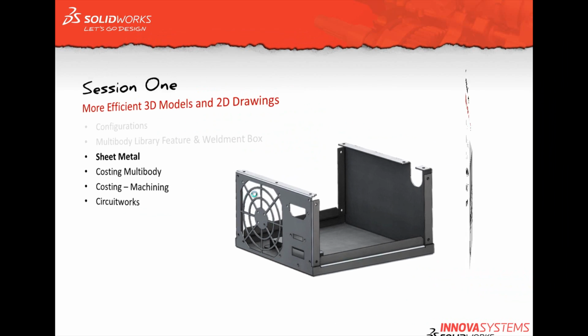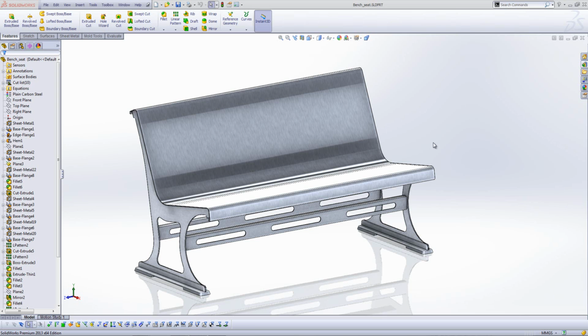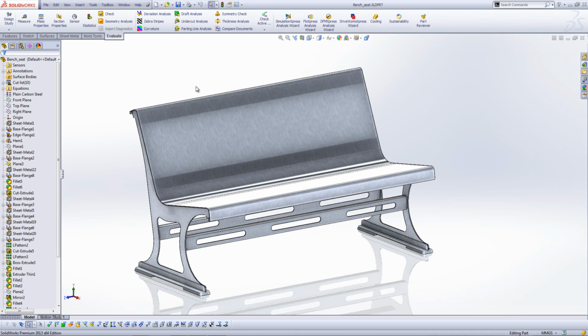We're actually going to stick with me for a little bit longer, and we're going to talk about multi-body costing. Okay, so costing was a piece of functionality that was brought in last year, which a lot of people really liked. It's part of the professional suite of products. So if anybody's interested in costing, that's the version of SolidWorks you would need to run to actually get this. In 2013 we've seen some additions to costing. What I'm going to talk about is the addition of support for multiple bodies. So on the screen here at the moment we've got a multiple body sheet metal part.